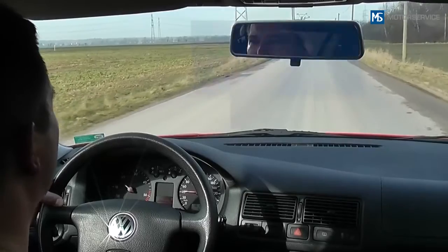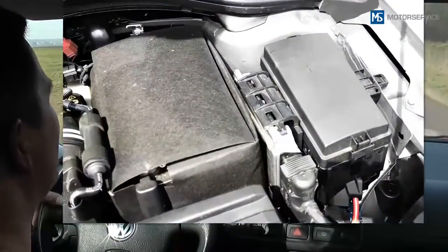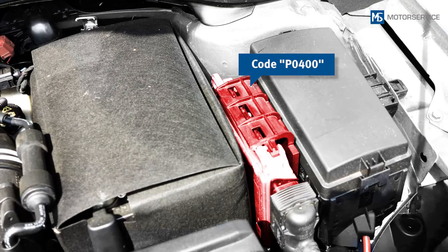If a fault occurs that compromises the exhaust gas quality, a standardized diagnostic trouble code is stored in the fault code memory of the engine control unit. The operating data and environmental conditions at the time the fault occurred are also stored, the so-called freeze frame data.